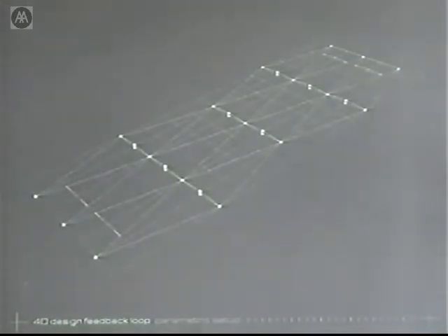And this is where I hit on the first problem, which is that any form-finding software for membranes that you can now employ operates only with static definition points. So as this multi-chamber component is obviously dynamic, when all the boundary points start to shift, I had to introduce somehow a combination of an animation and a membrane form-finding process.